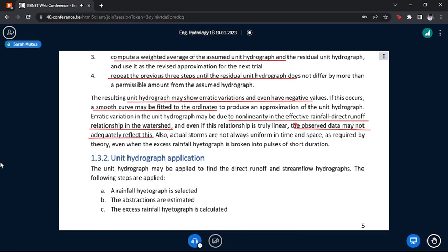And we said in hydrograph, storage S is equal to K, a constant, times Q. And normally the K causes the Q to decrease in an exponential manner. But other things will affect this. Many things affect this storage discharge relationship.